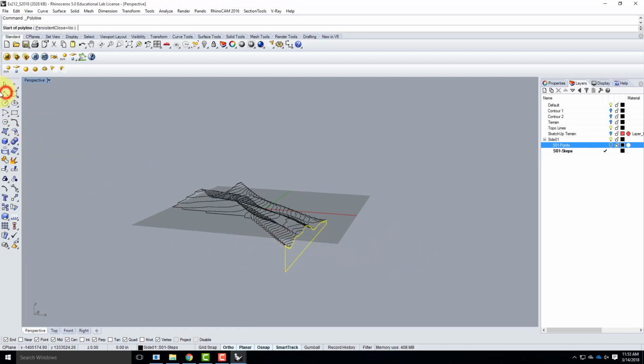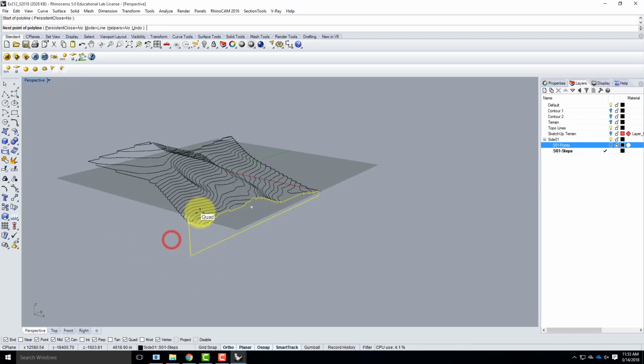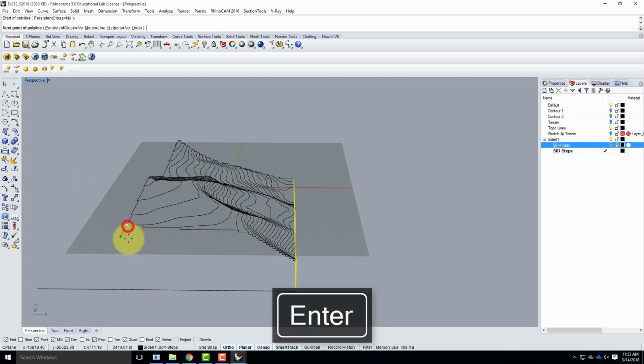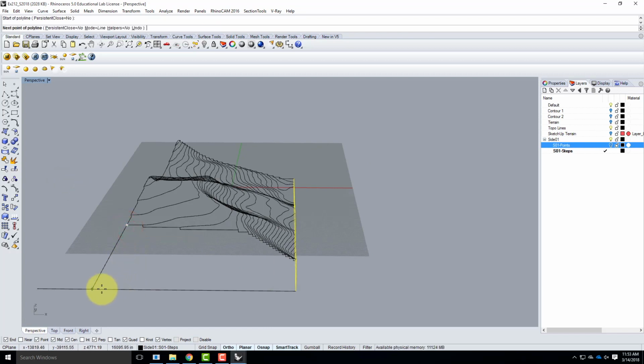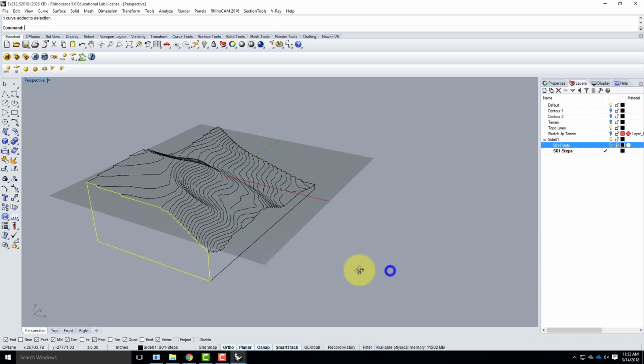So now I need to start making the rest of the sides. So once again, I'll start with the polyline tool. I'll come to this next corner. There it is right there. I'll go down. I'll make the height match at this corner, and I'll come straight across. Then I'll go to this upper corner, snap to it, come straight down to perpendicular. There it is, and hit enter. Now I can use this line to trim that piece. If I hold down Shift, I can select that piece plus this piece right there, and I can join those together.